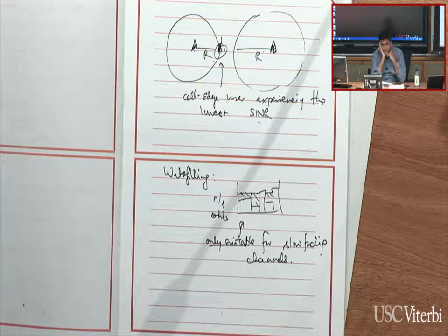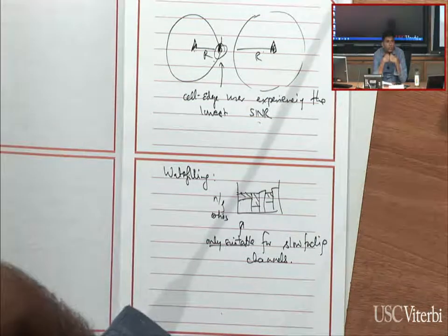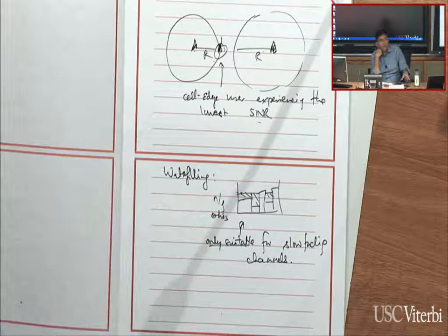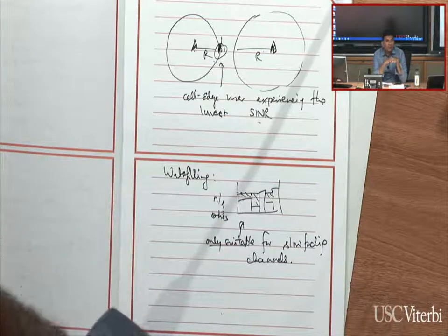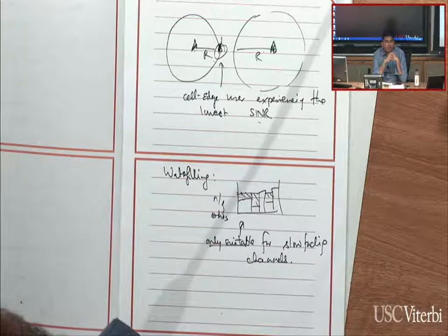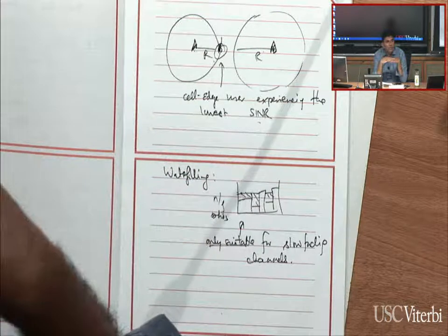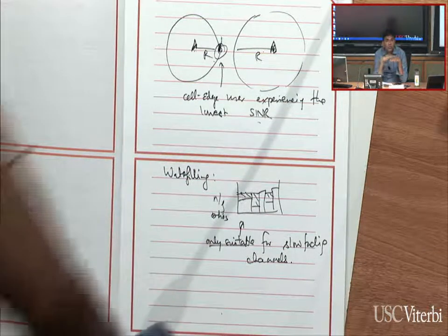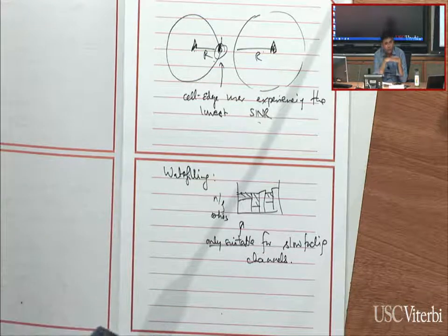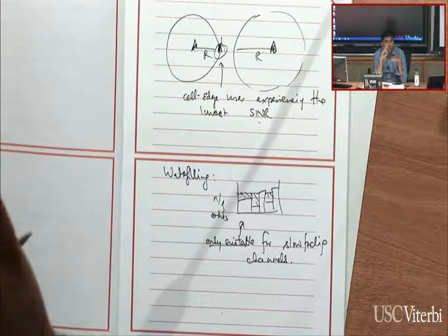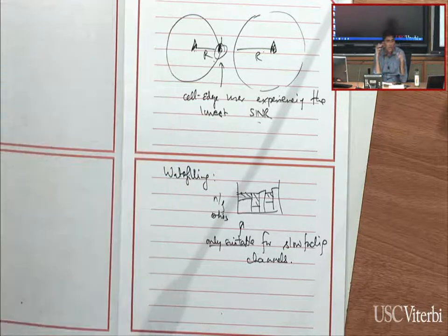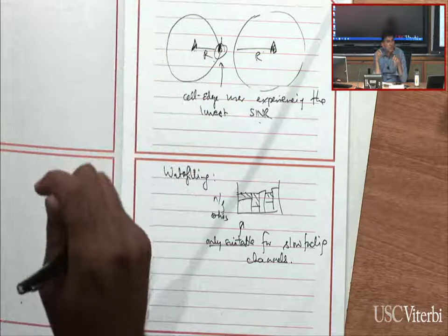What I mean by that is a channel in which the values are not changing dramatically, right? And so what this problem got at was, what if they were changing fast? If they're not changing fast, what you can do is send some signals, measure the quality of the signal, then figure out these ratios, solve that optimization problem, and then run it. But sometimes you may be in an environment where, because of the motion or people moving around or the traffic or whatever, the signal quality doesn't stay the same, this noise to gain ratio is not always the same value. In particular, even your noise power might be the same, but your gain might fluctuate dramatically from moment to moment as different reflections cancel or constructively interfere, right?